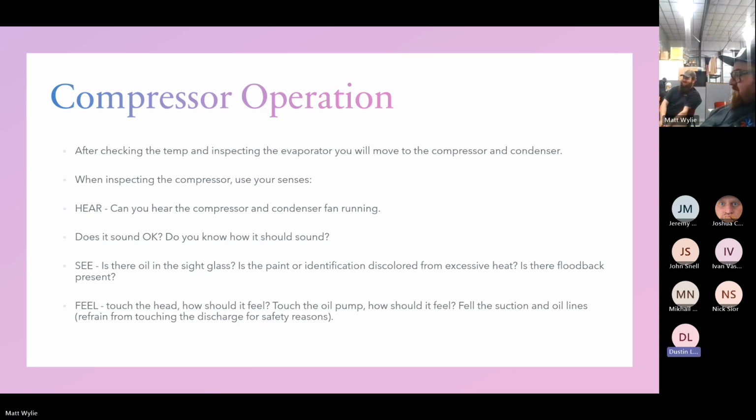I believe on single phase compressors, the ones with the start caps and run caps and relays, it's been a long time since I learned this, but isn't 1 and 2 plus 1 and 3 equal to 2 and 3 or something like that? I haven't heard that, but it could be possible. It's like common to start and common to run equals start to run, if you add the ohms up. I don't remember the exact equation. Yes, that's correct, they do add up. What you just said sounds about right, looking at the numbers that I get.